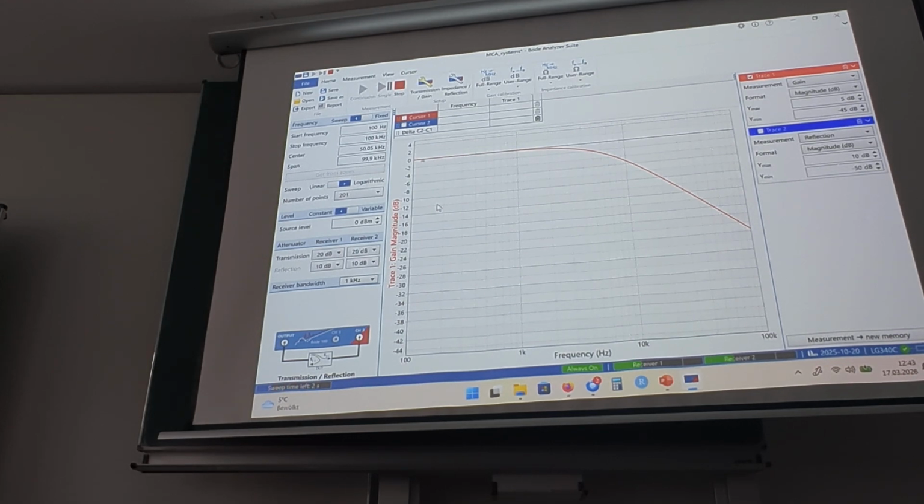So the device makes measurements, and in fact we see here a ratio of amplitudes. This is the voltage at the input across both elements, and the output is the voltage only across the capacitor. For low frequencies, it's the same. We have here units in dB. Are you familiar with decibels? If not, then you can change this.